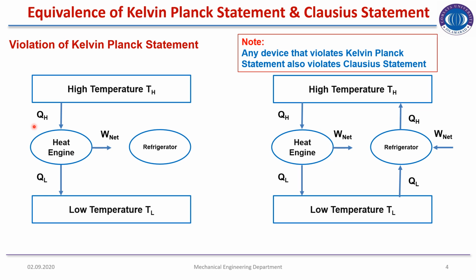Now we also have a refrigerator as shown here. The function of refrigerator is to receive heat from the low temperature thermal energy reservoir and eject heat at the high temperature thermal energy reservoir. So this refrigerator is receiving QL amount of heat from the low temperature thermal energy reservoir and ejecting heat QH into the high temperature thermal energy reservoir. In doing so, we have to perform some work or supply energy, usually in the form of electrical energy, into the refrigerator.